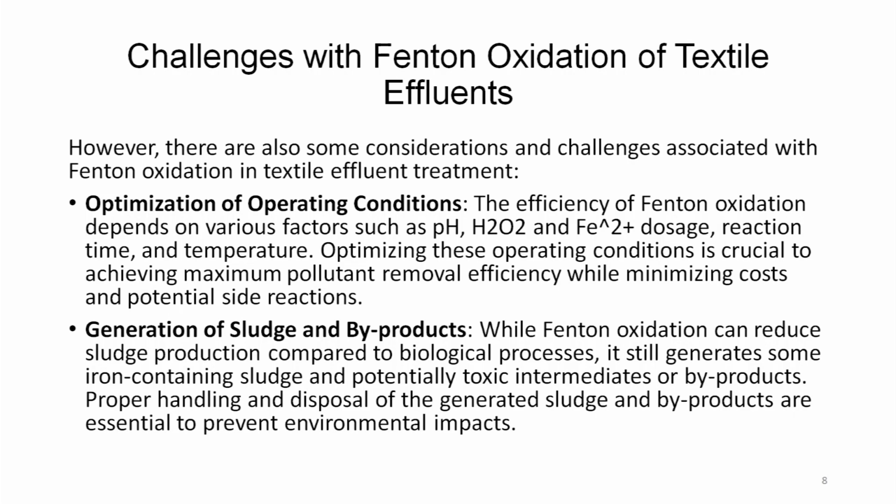Generation of sludge and byproducts. While Fenton oxidation can reduce sludge production compared to biological processes, as we saw a while ago, it still generates some iron containing sludge and potentially toxic intermediates or byproducts.